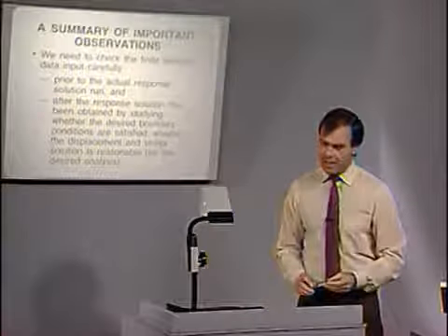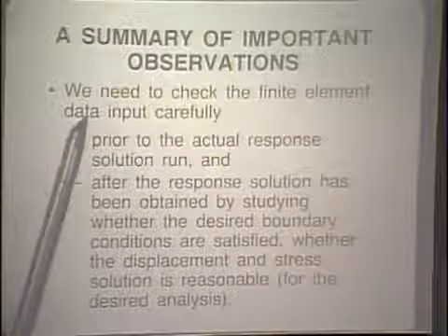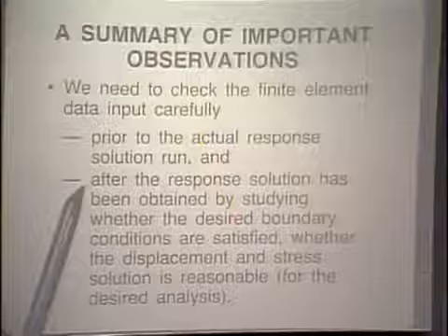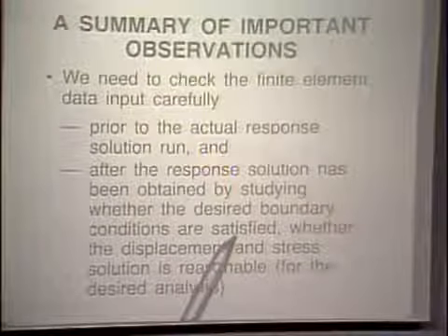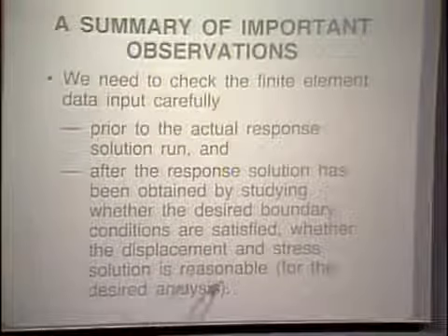Let us summarize some important observations regarding finite element analysis. It's important to check the finite element data, of course, very carefully. The data must be checked prior to the actual response solution. This is done, of course, with the preprocessor by plotting the data, looking at it very carefully, typically. And then, after the response solution, you still want to check the input data once more, by seeing whether the boundary conditions that you wanted to impose onto the model are properly satisfied, and whether the displacement and stress solution is reasonable.